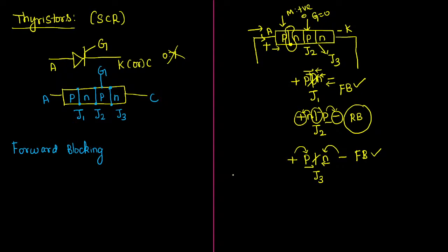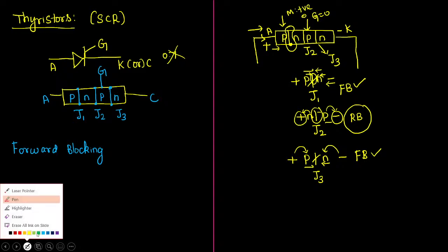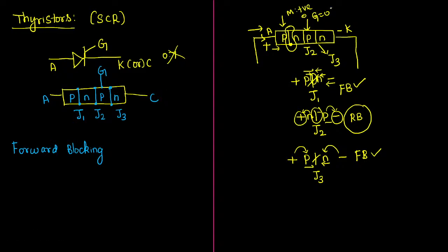In such a situation, can you turn on the device? No, sir. So for this circuit, you have injected positive voltage and negative voltage. But remember one more thing I told you: I have not given any signal to the gate yet. I haven't applied any signal; the gate value is considered 0. That is the beauty of SCR.